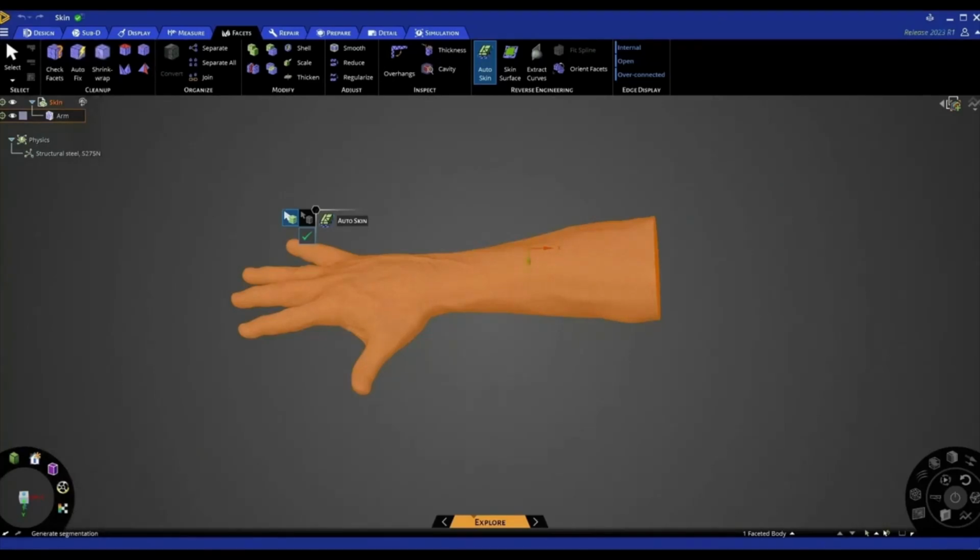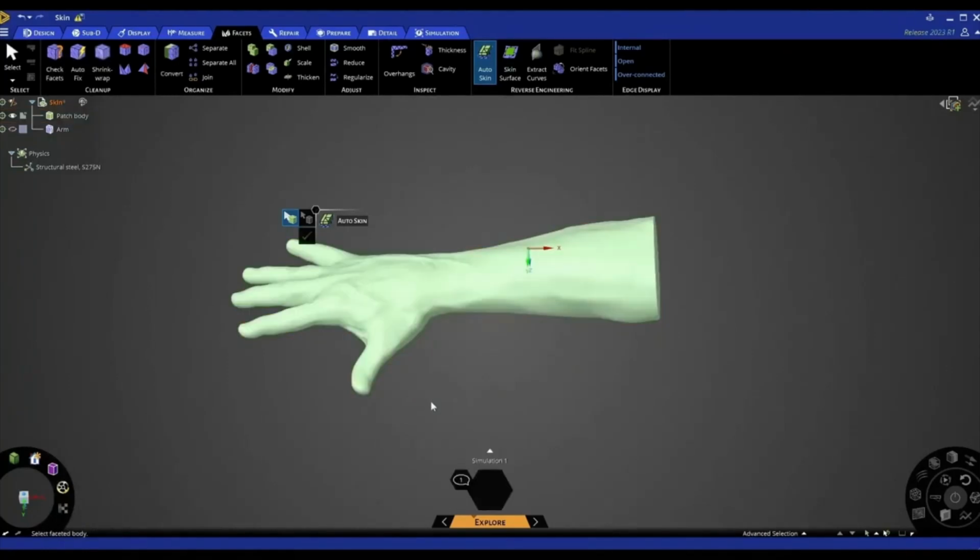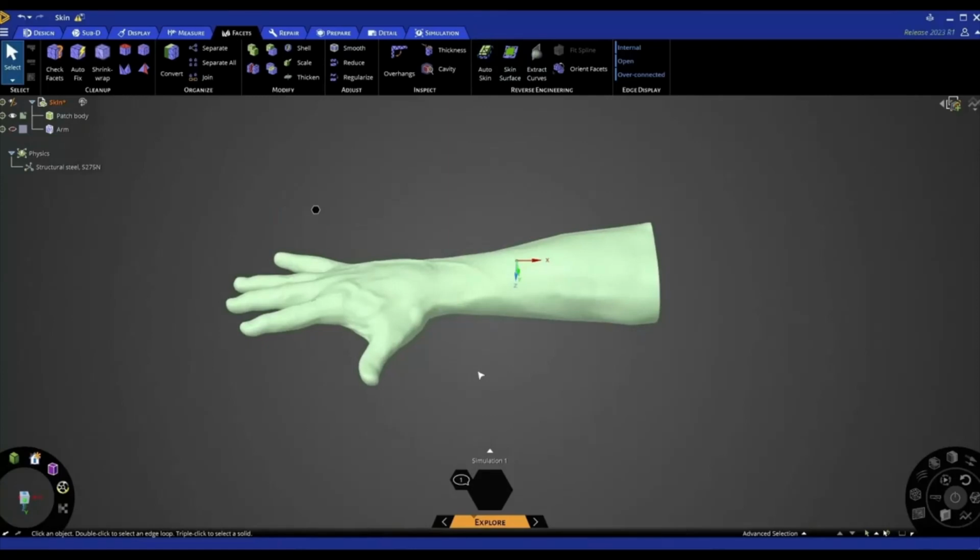But then it will create the curves, and then it will create the surfaces, the patch surfaces from the curves that it creates. So you can see down here in the left-hand corner, it's generating patches. Again, just flashing black. But it's going to have 122 different surface patches that are going to make up this solid body. So it has just completed.